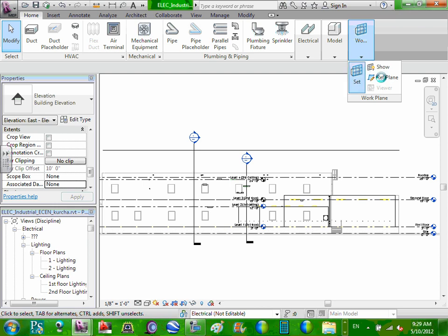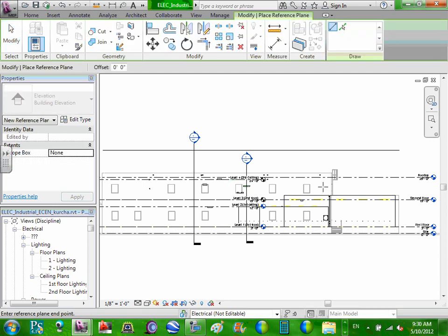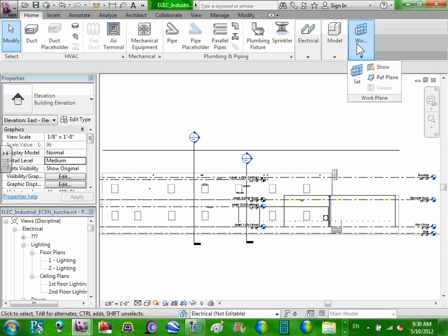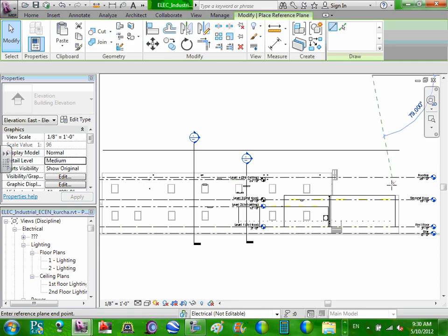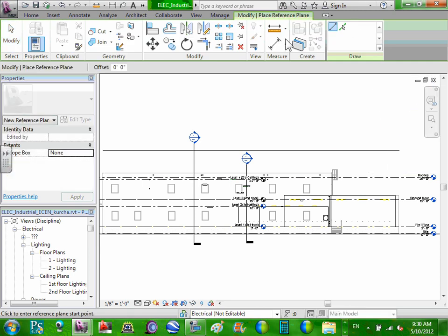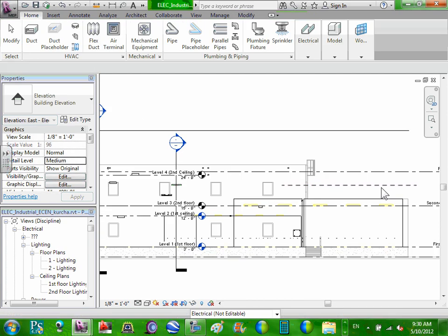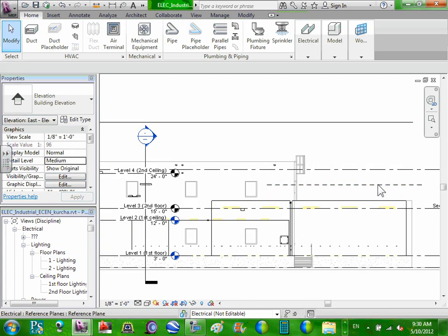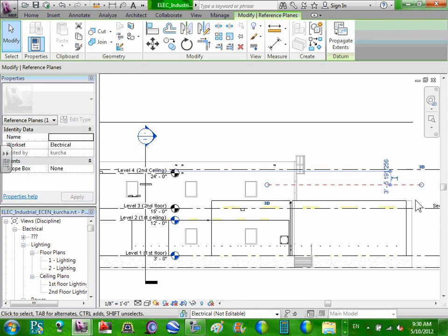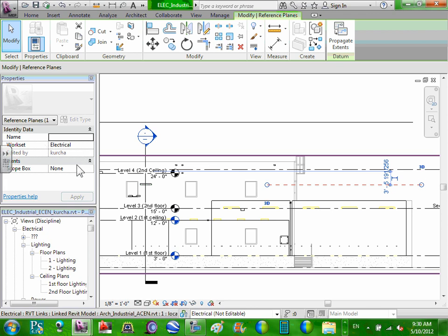It's work plane. Yeah. I would do a reference plane, which I guess is under the heading of work plane. And then depending on how you place that, left to right or right to left, and I can never remember which way. But that's why you always put one fixture down and then look at the section. It becomes a ceiling or a floor.